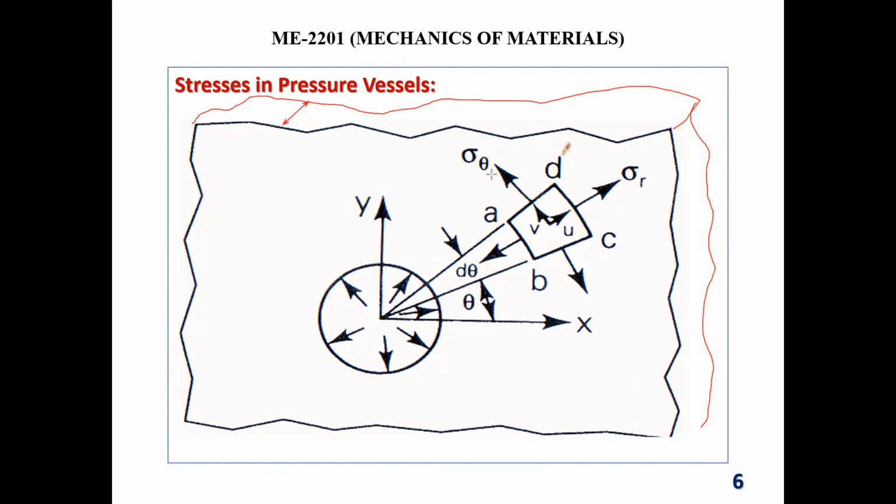Say the hole diameter D equals 3.0 inch. Now you would like to put a bush or a shaft, but the shaft diameter ds equals 3.005 inch. So what do you think? Will it go inside automatically? Obviously not. There is some interference, right?